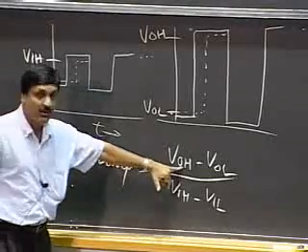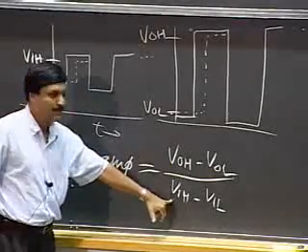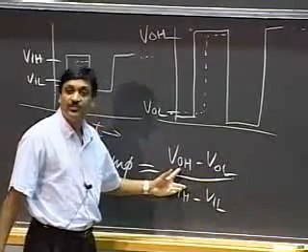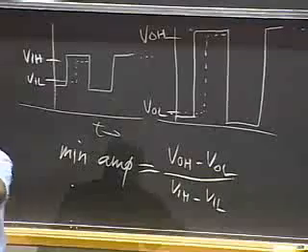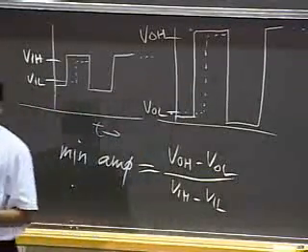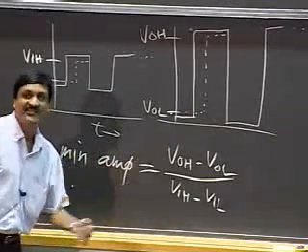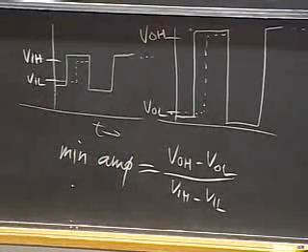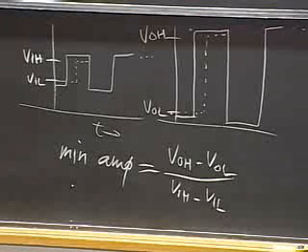Okay, and notice VOH is larger than VIH. VOL is smaller than VIL. Therefore, this quantity needs to be greater than 1. Okay, so I've shown you both a simple graphical, intuitive explanation, and this is a slightly more formal proof that even the digital circuit really requires to have amplification built into it if it is to satisfy valid static disciplines.